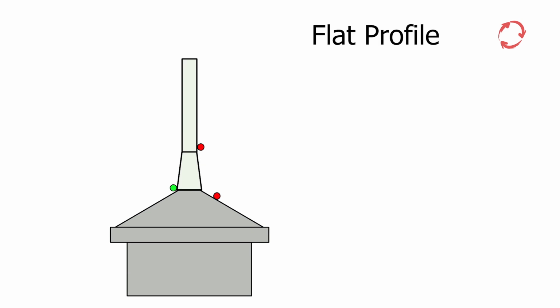For flat profiles, the mandrel is fixed in the head such that the transition from the mandrel base and the conical area is exactly flush with the upper edges of the head. There is thus no feed area. However, the following also applies to flat profiles. The exact setting dimensions have to be verified or determined via a test run.